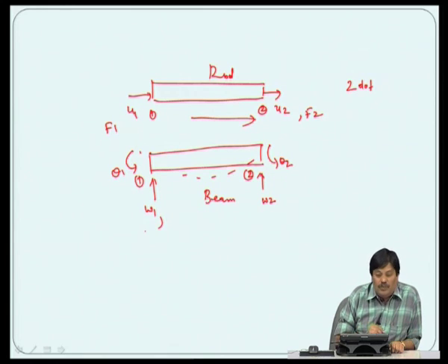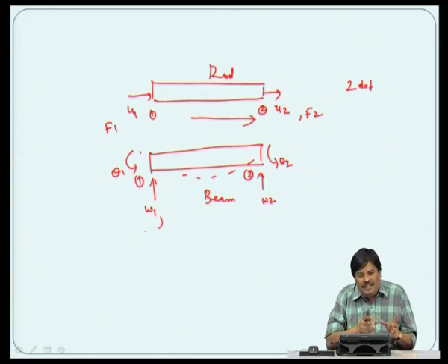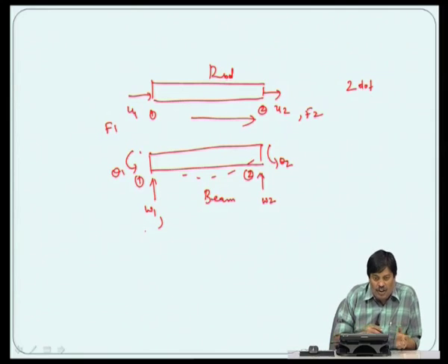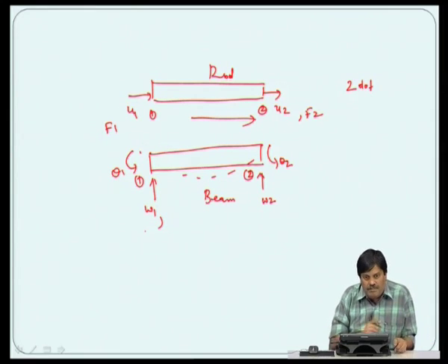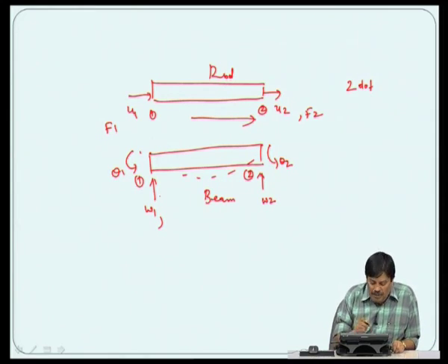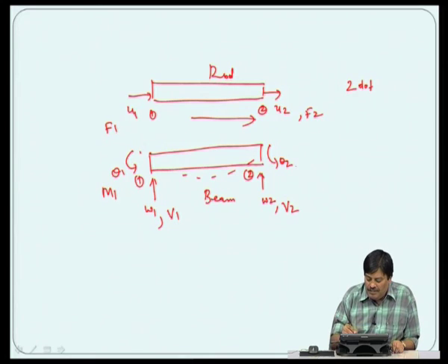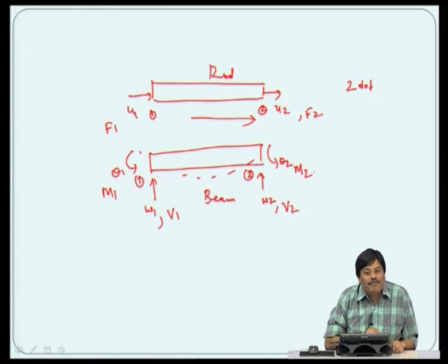Corresponding to the W1, everything will have a displacement variable and a force variable, what is cause and effect, as we found in the variational principle. The W1 is caused by the shear force 1, W2 is caused by shear force 2, and theta 1 and theta 2 are caused by the moment 1 and moment 2.